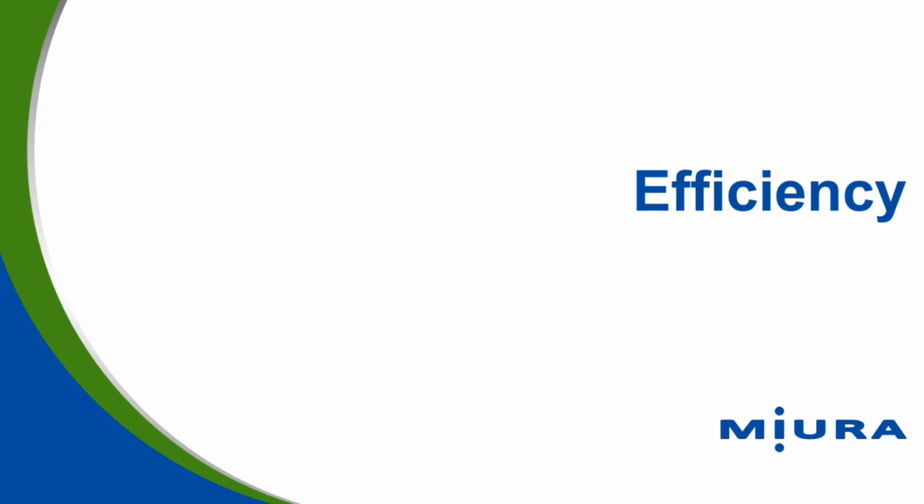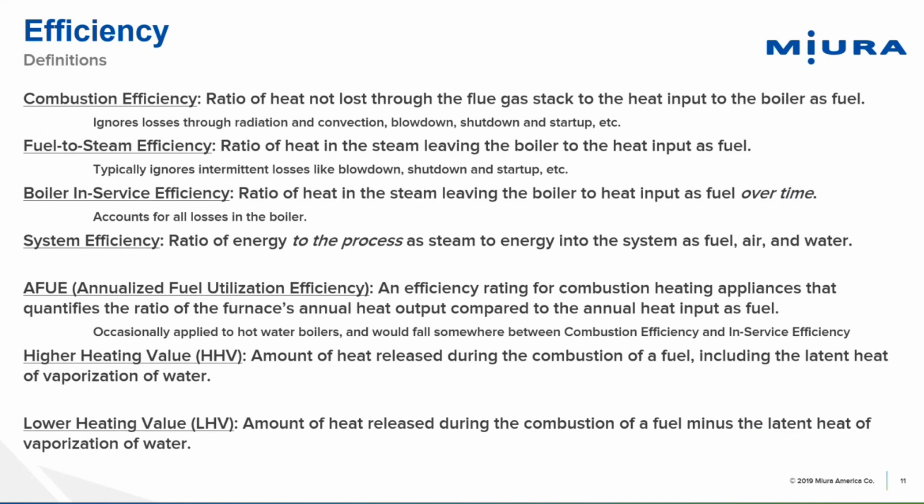All right, so next we'll move on to efficiency. So basically, what is efficiency? So we've got some basic definitions. The first being combustion efficiency. So you'll often hear people say boiler efficiency. They sometimes mean combustion efficiency. So what that is, the ratio of heat that's not lost through the flue gas stack to the heat that's input to the boiler as fuel. So you're ignoring basically the effectiveness of transferring that heat directly to the water. And you're just looking at how much heat did I take out of this gas before it exited through the stack. It's usually pretty simple to calculate. So it's a good one for that, but it's not really telling you the whole picture.